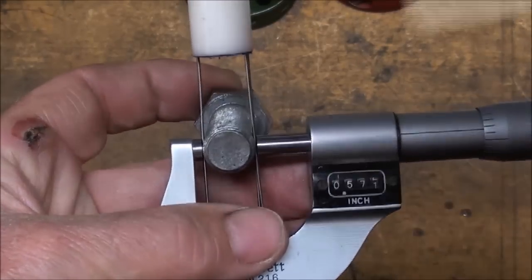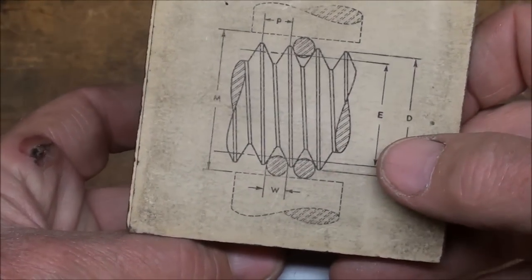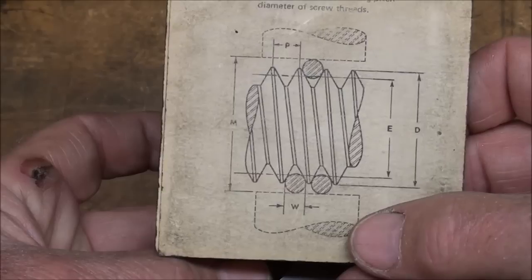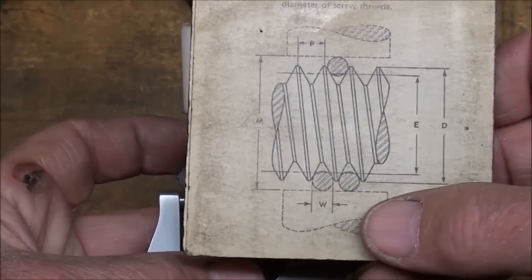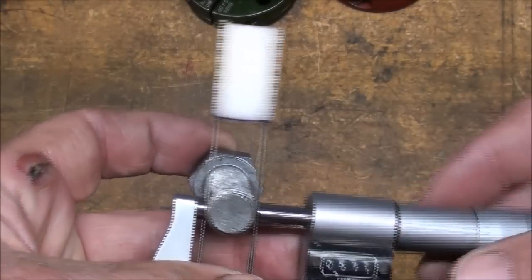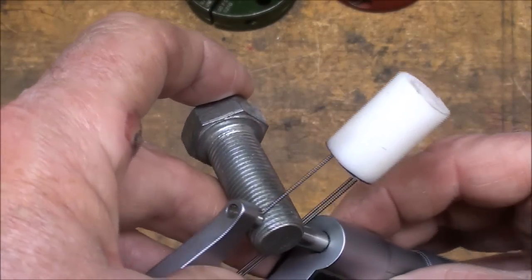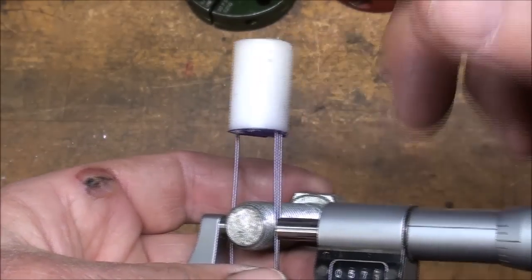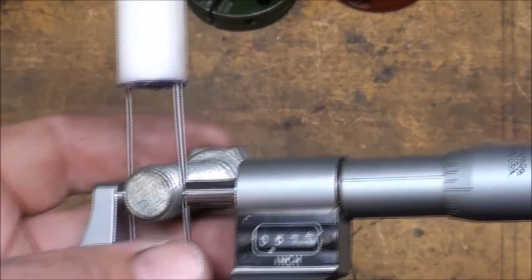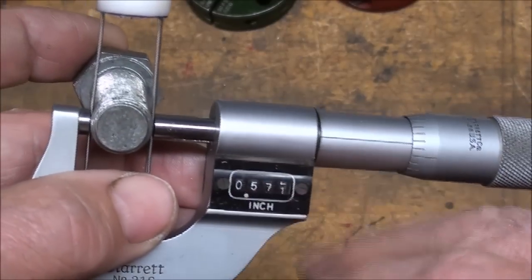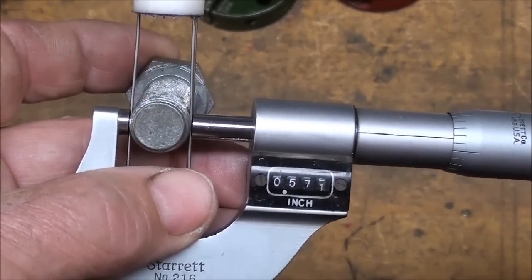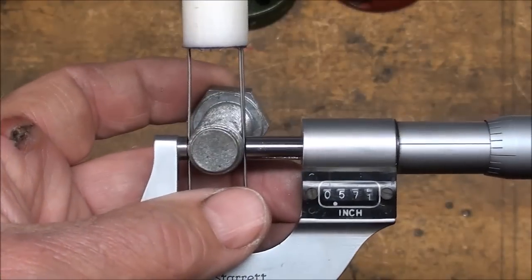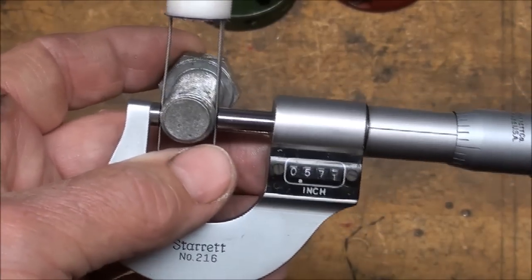If you look at this little chart that came with the wires, you can see the cross section of the 3 wires there, and now those are the anvils of the micrometer on the top and the bottom here, one my thumb is on. And that's basically what I'm doing here right now, is I'm holding those little wires, 2 on one side, 1 on the other. And this works slicker than can be with this little piece of Delrin that I've got here. And my dimension is 571. I'm going to write that down, and that's for the commercially made bolt, and then I'm also going to measure the one that I cut on the lathe yesterday.